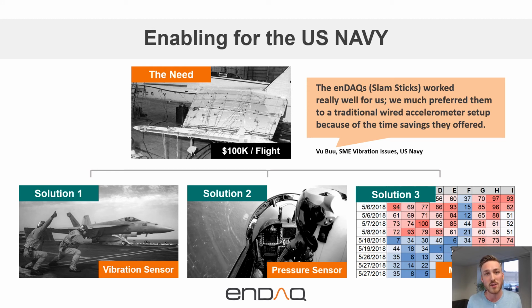When the Navy experienced this hypoxia event where pilots were experiencing hypoxia at some of the flights, they were really concerned and wanted to measure pressure in the cockpit. They didn't have a sensor that was flight qualified that included a pressure sensor. Our system, we had thrown in the pressure sensor in the development, and they started using our device to measure the pressure trace of every single flight, so that pilots could report that they had an event when they had an event and could be treated appropriately, as well as getting that pressure data to figure out what was causing the problem and fix it.